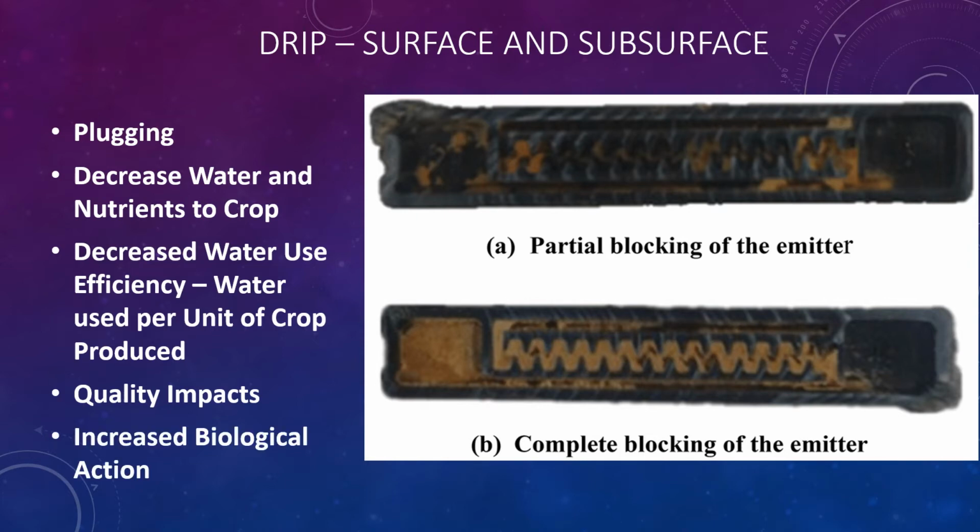And then, of course, within the line itself, now not only do I have silt issues, but now I've got increased biological action, which means I've got to do more flushing, and that's probably the biggest thing: the flushing and the impact on your system. It's very hard because these things are buried, unlike a lot of them in a surface situation, so it compounds the maintenance issues.